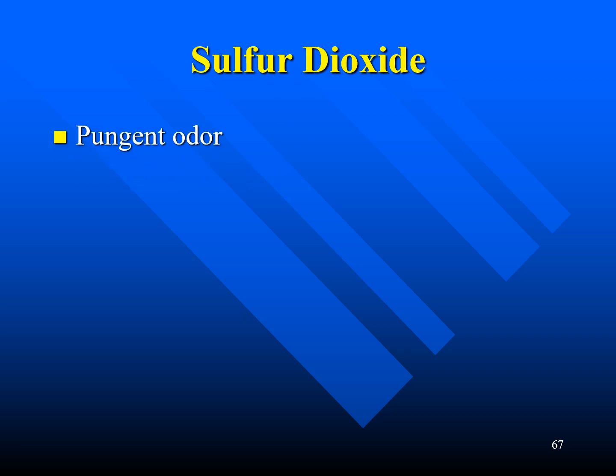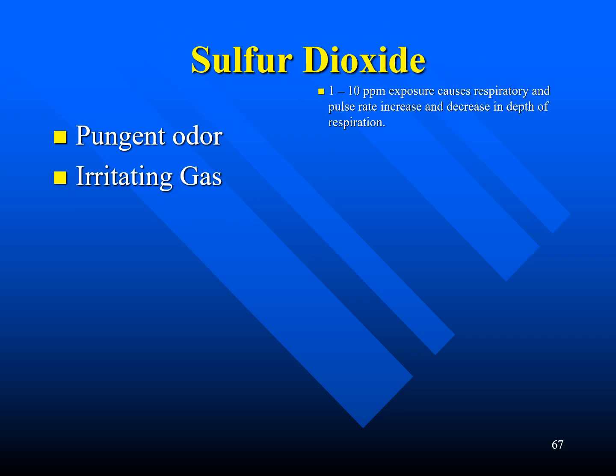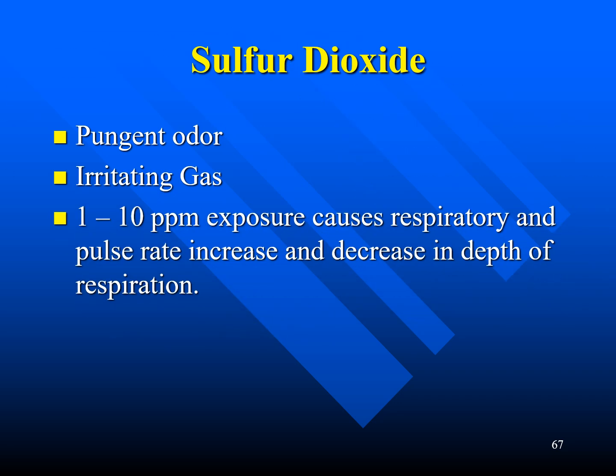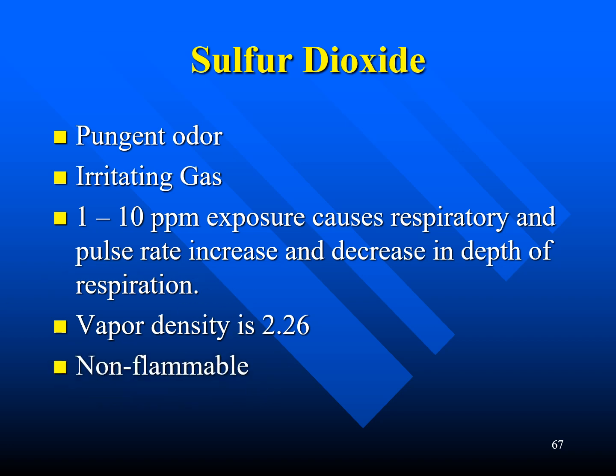Now let's talk about sulfur dioxide, which is another gas that's commonly found in confined spaces. It has a pungent odor. It's an irritating gas. Exposure at 1 to 10 parts per million will cause respiratory and pulse rates to increase, and you'll also notice a decrease in the depth of respirations. It has a vapor density of 2.26, which means it's heavier than air, and it's non-flammable.